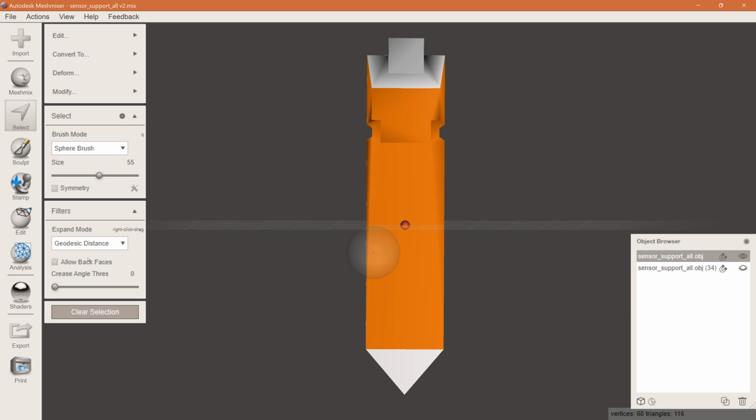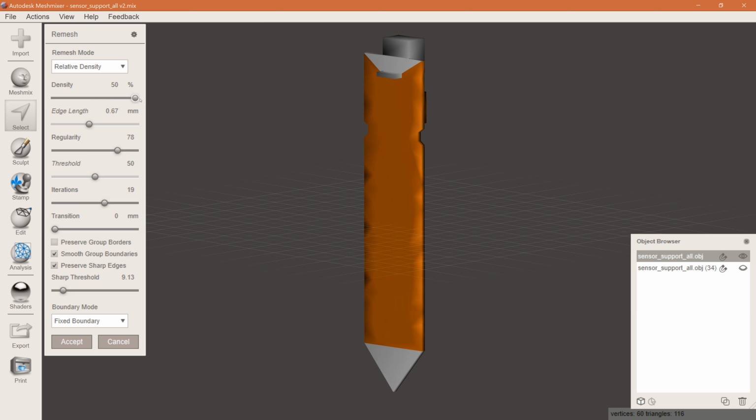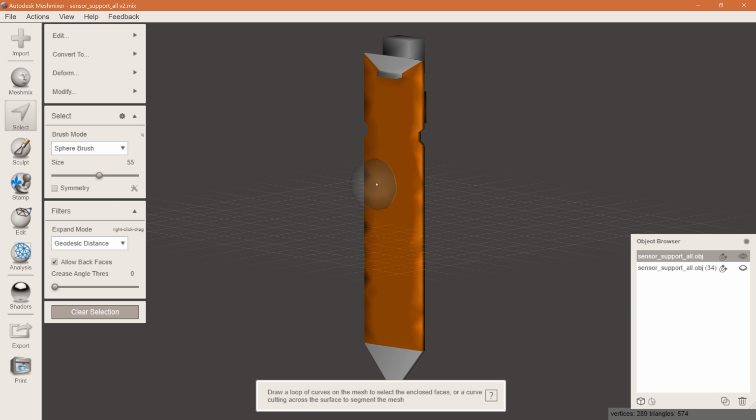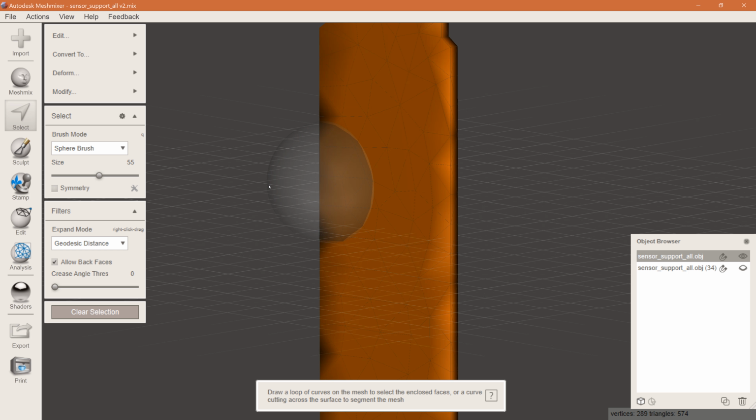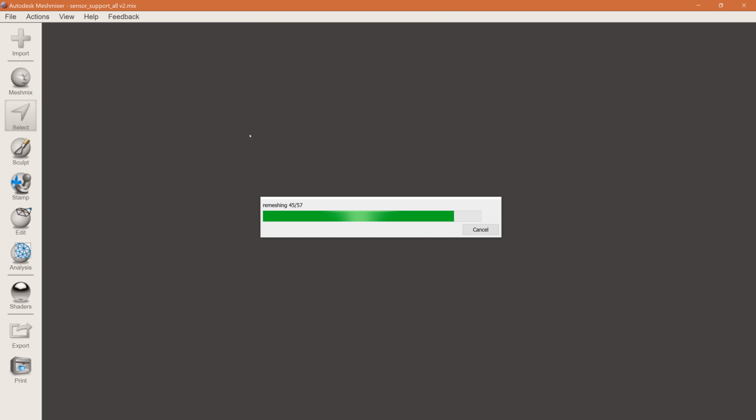So here I'm getting into the remeshing. Whenever you're doing intersecting or differences, you want to have a lot of triangles. So as you can see, that reference part only has a few triangles to begin with. So now I'm selecting all the areas that intersect with the part, and I'm increasing the face count. And I'll do that several times so that there's a lot of triangles.